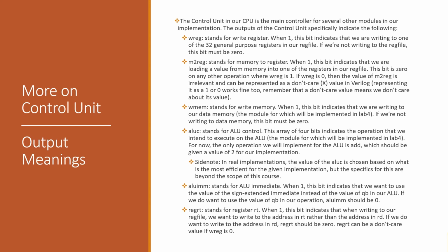WMEM stands for write memory. When this is 1, this bit indicates that we are going to be writing to our data memory, which we'll implement that module in Lab 4. If we're not going to be writing to our data memory, then this bit must be 0.